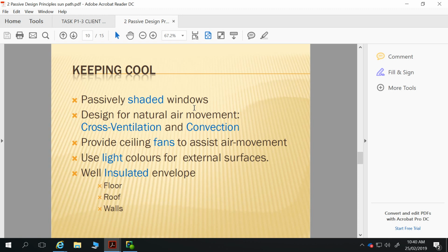They are more than a decorative feature. They restrict that convection current of air past the window. Let's say we got rid of our curtain, we just had the pelmet there, and we had this motivation for that warm air pulling up like that. As soon as we put a pelmet there, it restricts that airflow, and the air has to go around that. It slows that process down of convection past the window.